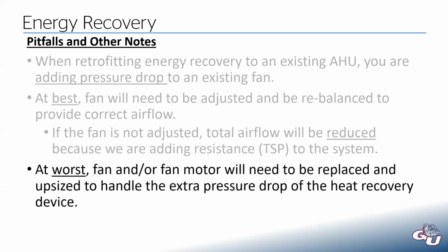Worst case condition, you might have to replace the fan or the fan motor. In that previous example, where we were adding 0.75 inches of water column to an existing fan, what if that fan or that motor doesn't have the excess capacity to handle that extra 3/4 of an inch? That means you have to replace the fan or the motor. Maybe you have to go from a 3 horsepower motor to a 5 horsepower motor.